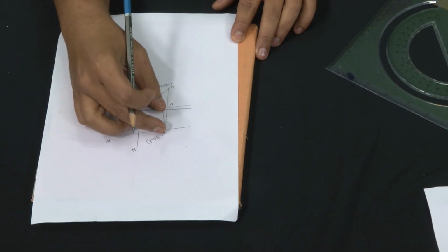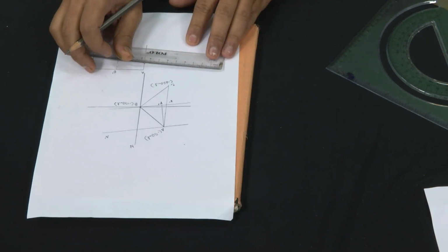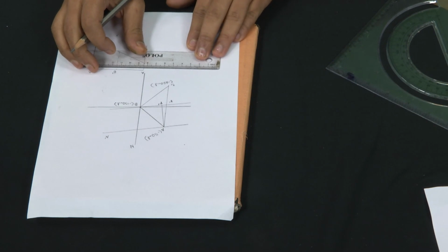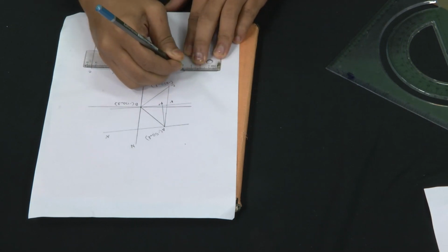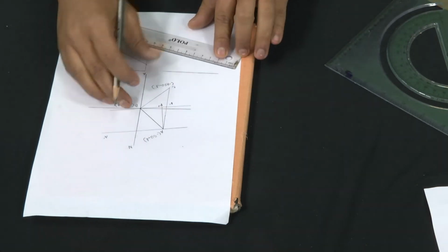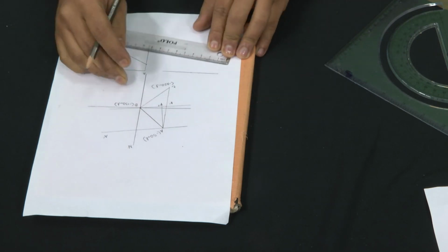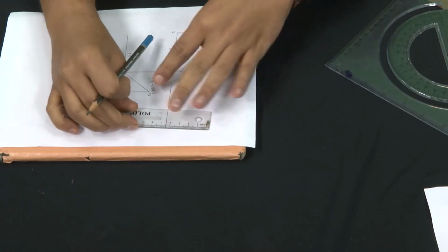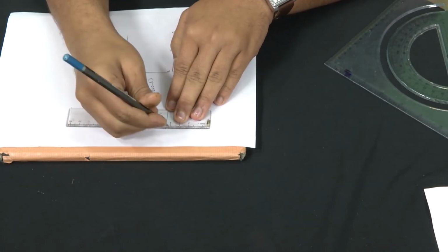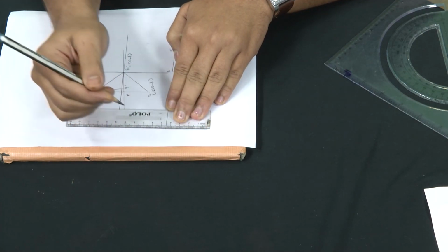In order to find out the dip, we will first construct another subsidiary diagram in which along the x axis we will plot the distance of A P dash, and now we know the vertical spacing between the A P dash, which is basically 80 meters.